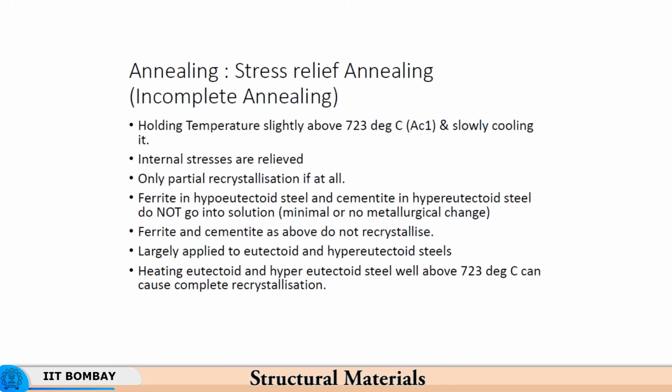Well, partial recrystallization may occur because different grains are at different stress levels. So, you may have partial recrystallization taking place, but we do not expect partial recrystallization at this temperature, but yes, we allow for a very small amount of this event to take place.